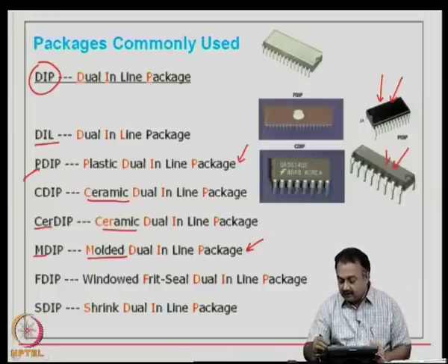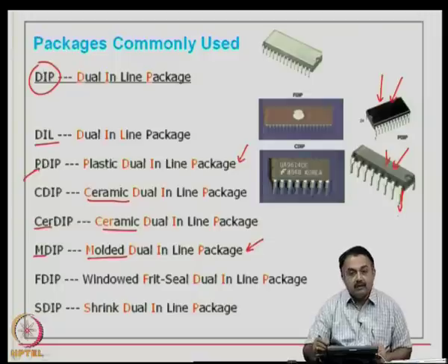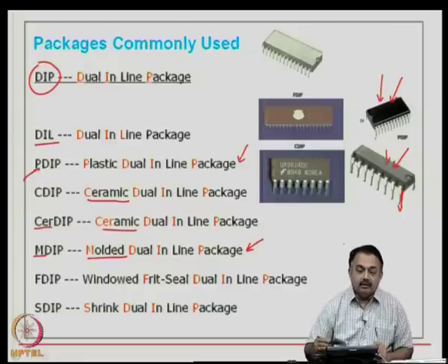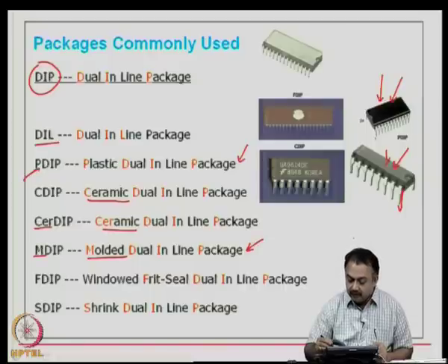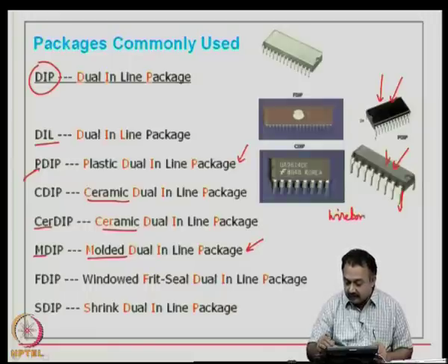As you can see that these packages have a very long lead length. Okay. So, it basically is built on a lead frame, okay, and we have also looked at what is a lead frame material. And then from the lead frame, if you rip open this package inside, you will see the die has been wire bonded. So, typically you can expect a wire bonding to be done from the inner die to the lead frames, right.